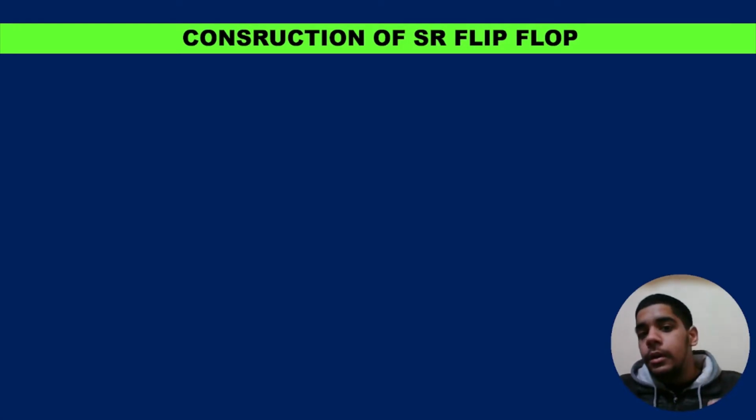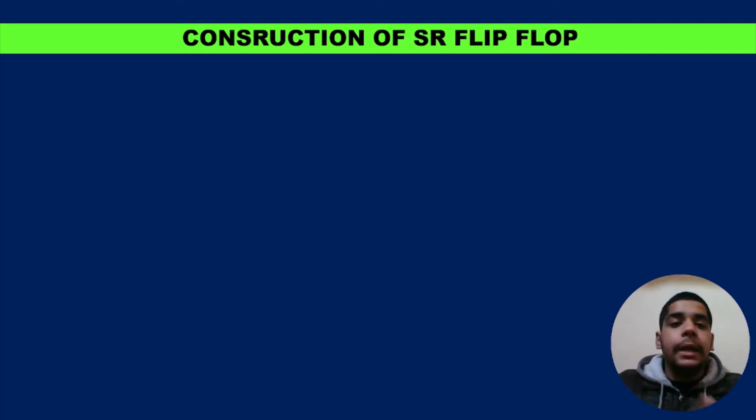So before starting with the construction of the SR flip-flop, I would like to tell you that we can construct the SR flip-flop in two manners, either using NAND gates or using a combination of an AND and OR gate. For this seminar, I am going to construct each and every flip-flop using NAND gates. So let's get started with this.